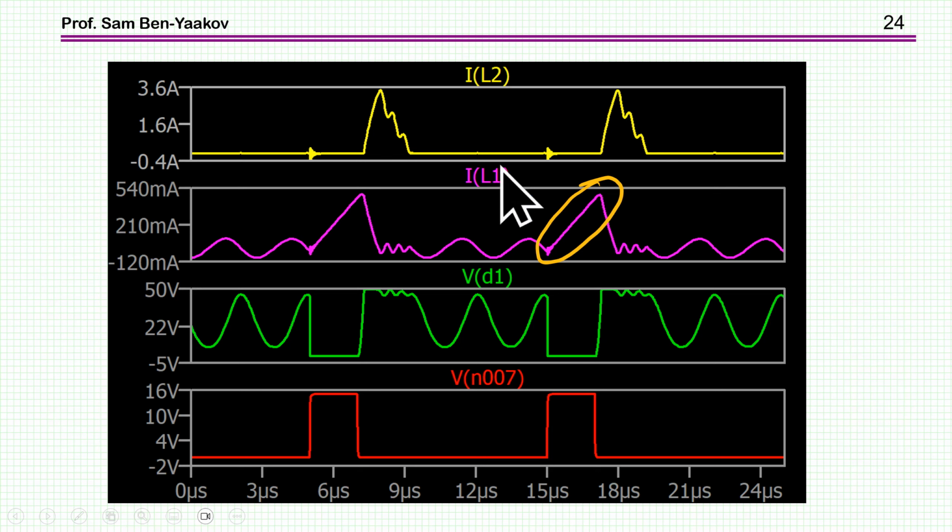And indeed, when I run the simulation with this clamp, you see a very fine line here, the rise of the primary current, meaning that we don't have this oscillation, we don't see it here, and obviously we don't see it at the secondary, which is the origin of this oscillation in the case that there is a capacitance of the diode.